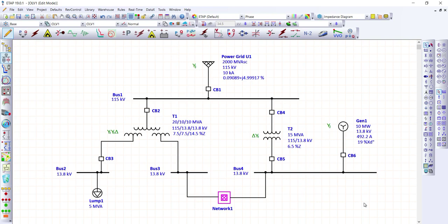The majority of power systems operate at a lagging power factor due to inductive loads and delivery apparatus, that is, lines and transformers. Power systems are inductive in nature and require additional reactive power flow from the power grid. But excessive reactive power demands result in reduced system capacity, increased losses, and decreased voltage, as well as higher operating costs. Shunt capacitor banks are able to compensate for VAR requirements.